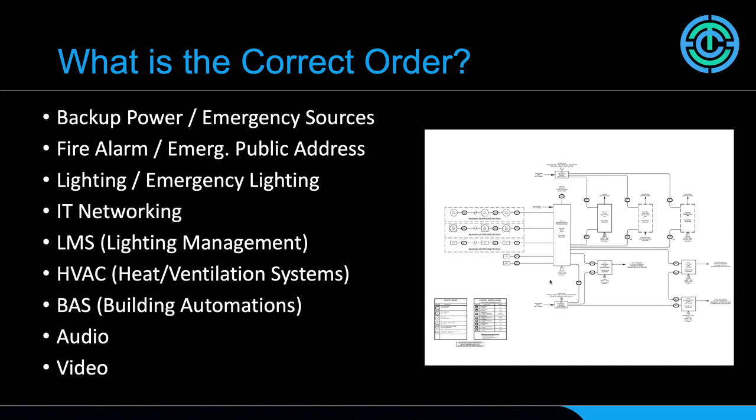There's many applications where we would be pulling the fire alarm status or emergency public address requirements to bring down the background audio in a building, bring up the lighting for egress, to allow announcements to happen, or even in the visual environments, change our display screens to give visual notifications for the hearing impaired that there is an emergency state going on in our buildings.